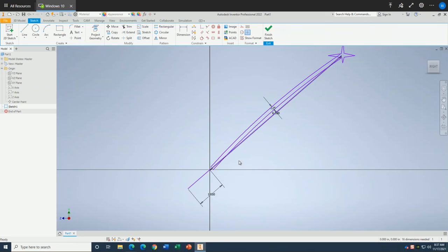Okay, far better. And I'm going to draw a circle because you need an axle. An axle has to be located against the circle. And then we need another circle, perhaps like that. An offset command would have helped here. So I'm going to try an offset of 1/8 of an inch, so that's 0.125.